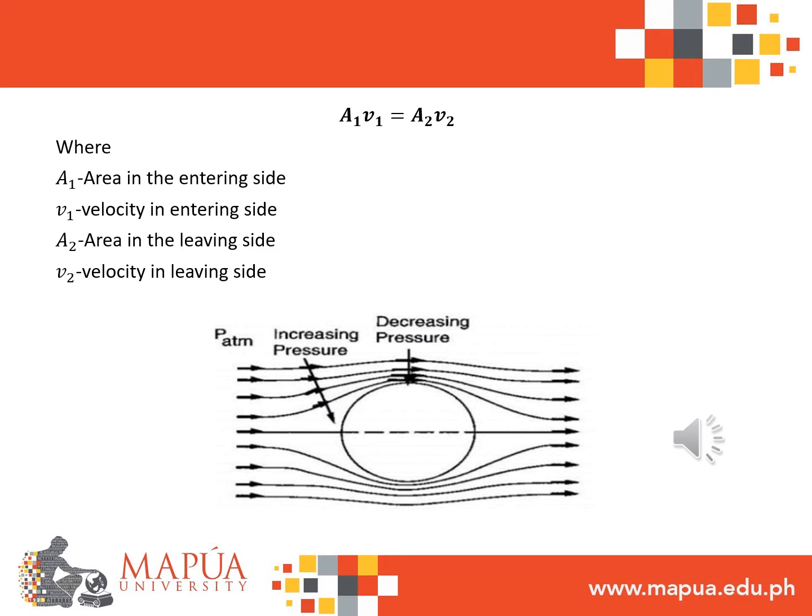Aside from the increase in velocity, the region at the top of the surface area of the sphere will have experienced a decrease in pressure based on Bernoulli's principle. Taking the continuity equation and Bernoulli's principle into consideration, we can see that a larger surface area is the one that produces the lower pressure region in the system. Along with the Bernoulli's principle and continuity equation, we can explain how and where low pressure and increase in velocity and vice versa will be generated in the system.